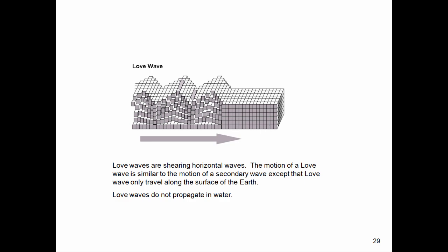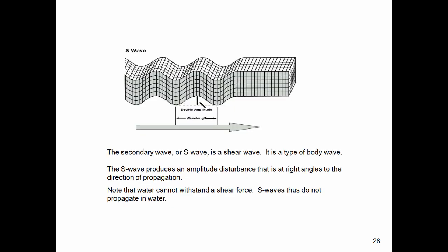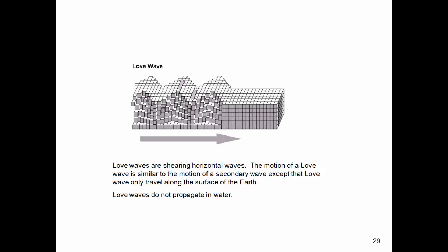Well, it turns out it's the two surface waves, the two waves that propagate along the surface of the Earth, that can cause the most potential damage to a tall building or launch vehicle. So imagine a tall cantilever beam here. This Love wave would shake that cantilever beam in the axis that's perpendicular to this slide, or you could say the axis that's out of plane with this slide.